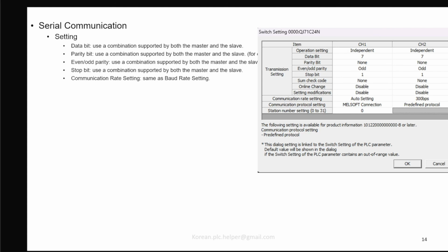Next, let's discuss the communication control setting. Earlier, when explaining UART, I briefly introduced the 4 main registers. This time, we will look at the settings associated with the control register. The control setting includes the data bits, parity bits, stop bits, and other communication parameters.